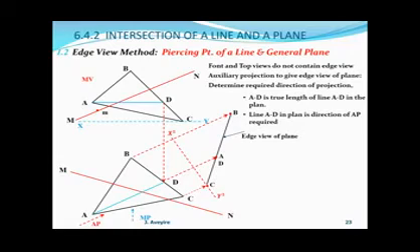Now we have to locate that point on the top view. So we project downwards and locate M on that view. Then now apply the auxiliary projection AP to M on the top view, and that will be that direction. Now we look at the front view and find the distance from XY to small m. That is a positive direction. So we come over here and plot that in the auxiliary projection.